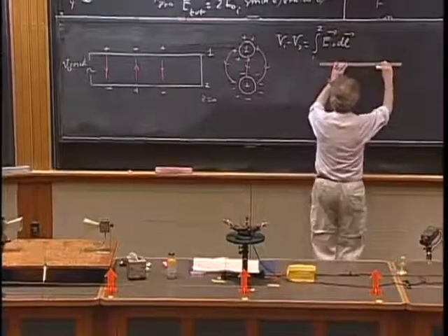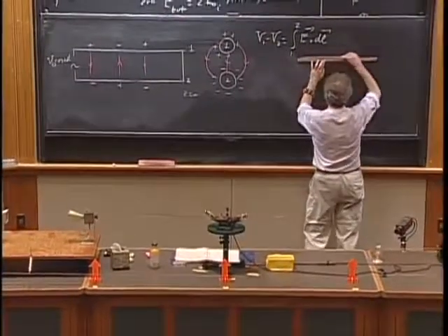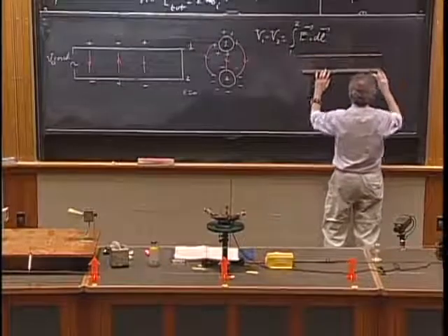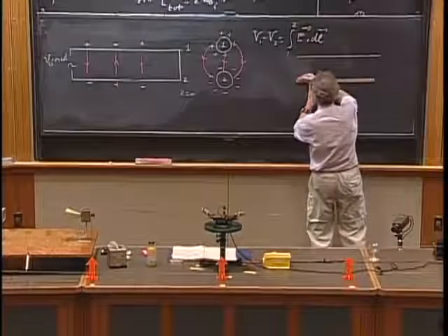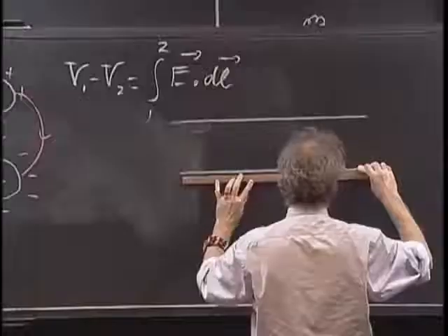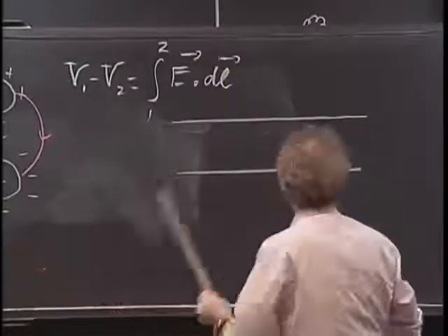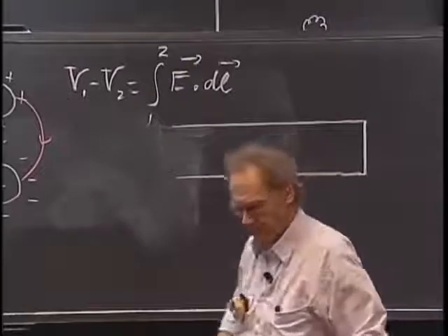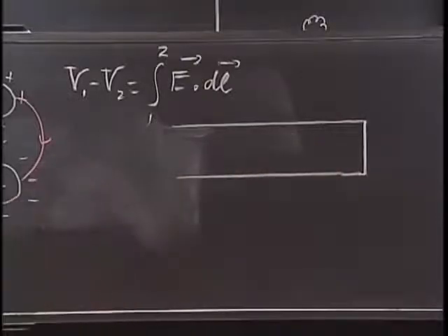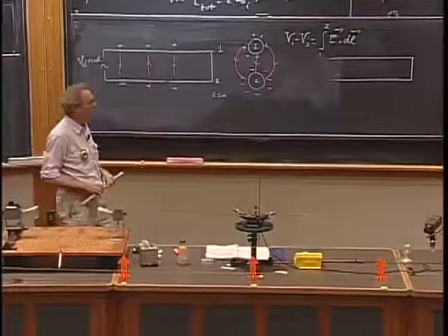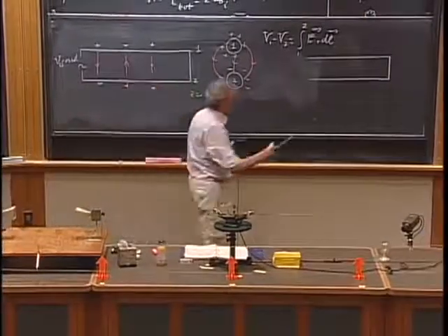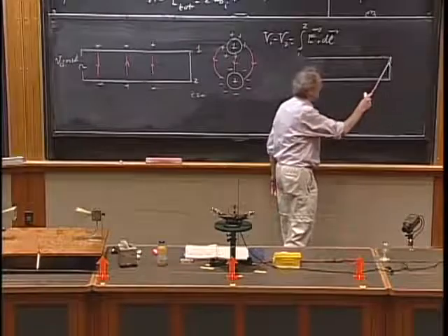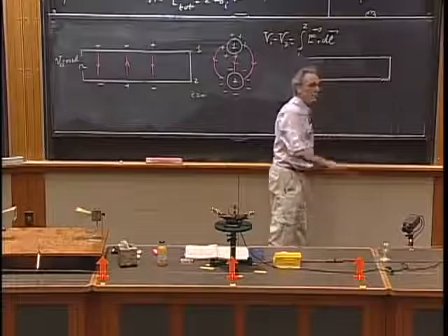And so here is the situation that the end of the lines, which by the way is there, that the end is shorted out. If it is shorted out, it acts like a conducting wall, just like with what we discussed before. There cannot be any potential difference between here and here, because the E field in this direction must be 0.